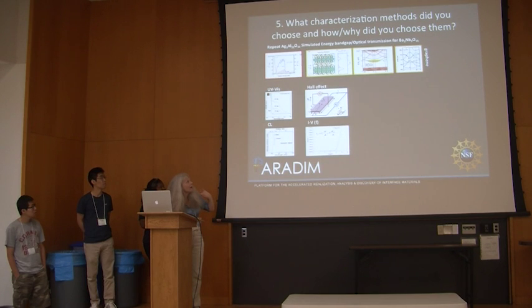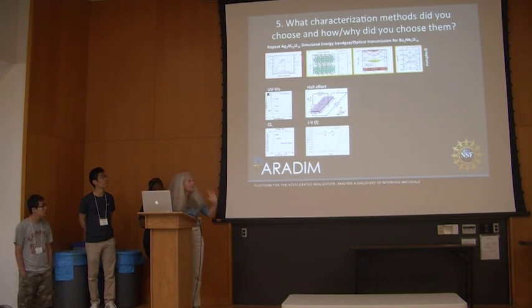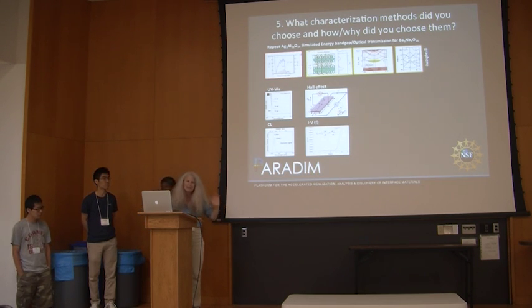The electronic conductivity is the practical property we want. Hall effect is the tradition for that. I would also suggest an IV curve that is taken in a frequency-dependent manner to see if there are parallel paths in there.